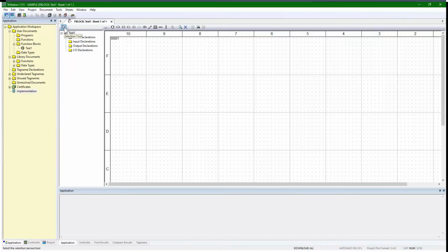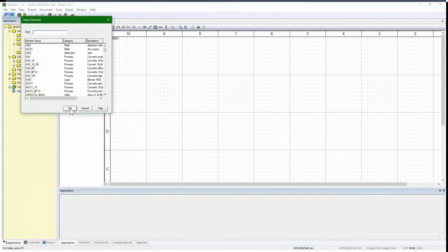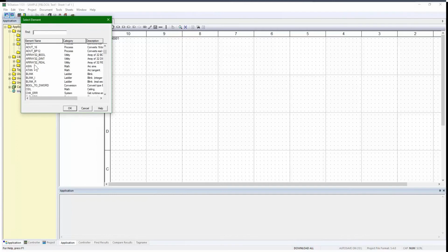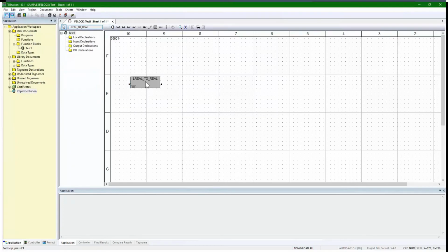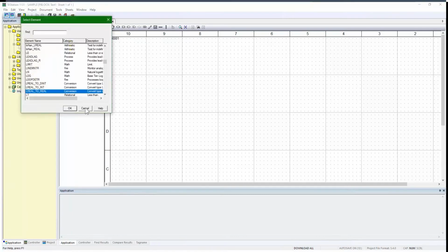Above it, you have your selection tool. This little blank here, you can type in or you can select. So here it lists all the function blocks that are available. And you would just select one, say OK, and place it. Then you have your ellipses where it brings up that menu again.